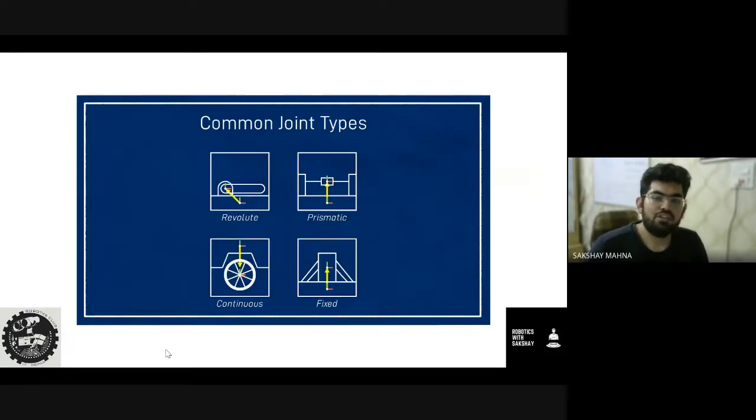The joints can be of different types. Before, we saw a special case, the fixed joint. Joints are made of many types, but for our purpose, we are only going to discuss four. And for the complete session, we are only going to use a single moving joint, which is the continuous joint. So let's discuss what these joints are. A revolute joint is simply a rotation joint. We can imagine this like a door joint, where the door only rotates about a fixed axis. So a door-like mechanism uses a revolute joint. One key thing to note is that in a door we have a limit up to which we can open and close the door. So a revolute joint has a maximum and minimum limit attached to it.